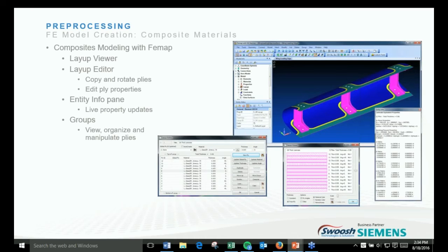With the ever-increasing use of composites in materials manufacturing, the need for good analysis tools within the design of composite materials is becoming more and more important. FEMAP has various capabilities to help you quickly view and understand the existing model or create a new layup from scratch. A big challenge with modeling composite materials is visualizing the model in layups. FEMAP's grouping functionality can help here, as you can define groups by layup, which makes visualization easier.